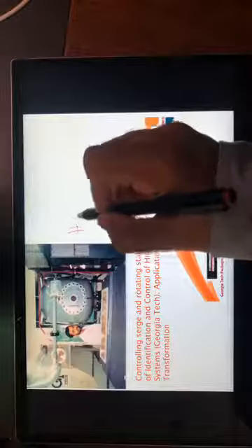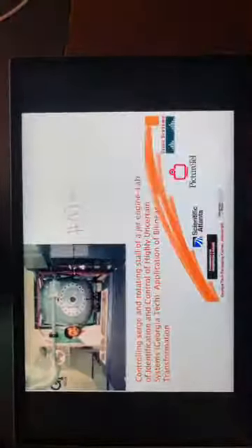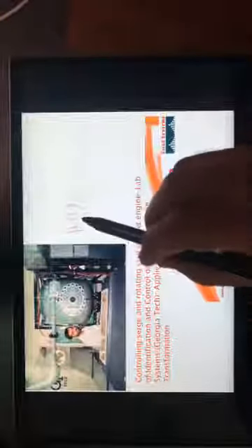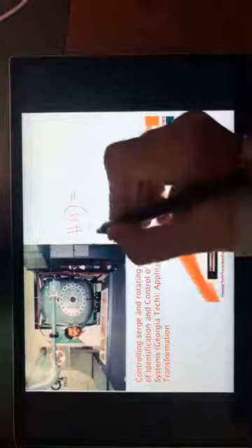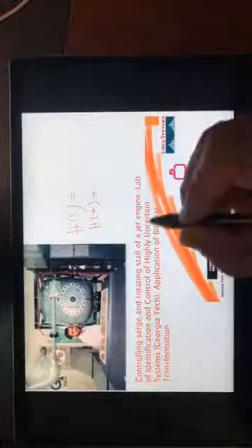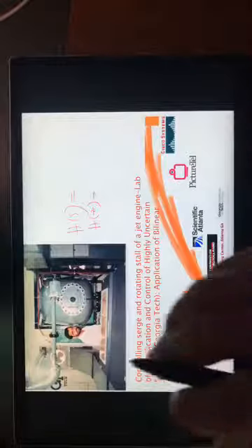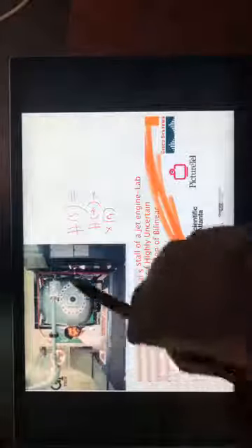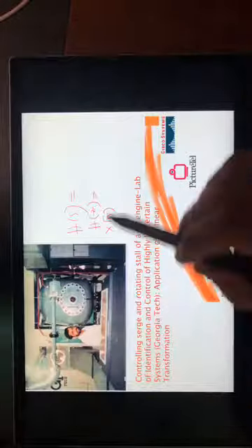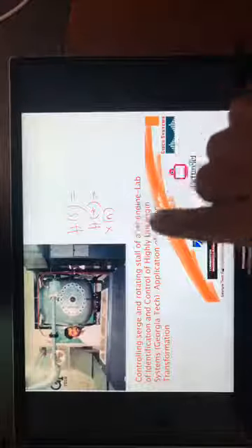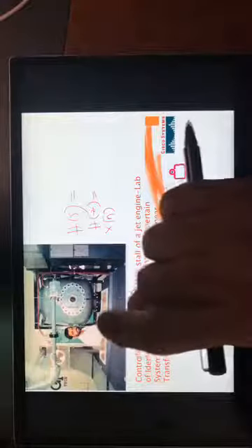and there were these crazy aerospace engineers who would design a transfer function H of S. They would give me a transfer function, and my job was to use this transfer function, convert it into H of Z, convert it into a difference equation, and then simply implement. So my input x of n was the pressure sensor in some part of the engine, and my output was the actuating signal I give to a bleeding valve to bleed some of the air.